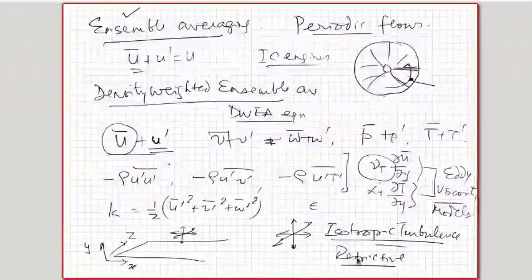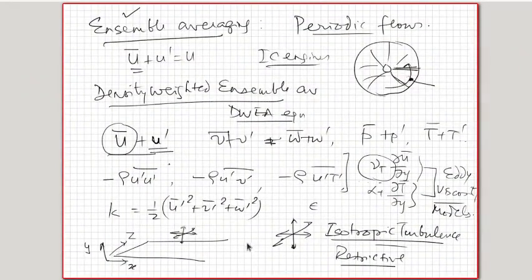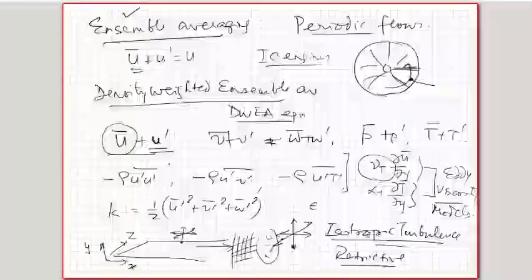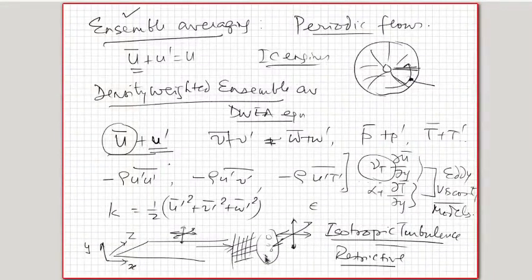Okay, what causes an isotropic turbulence is probably a grid. Say for example, if I have a wire mesh through which a turbulent flow leaves, and there are eddies which are of very similar size to the size of the mesh that are formed here. In this region, the flow will be isotropic, the turbulence will be isotropic. But other than the grid turbulence of this kind, everywhere else the turbulence is going to be non-isotropic. So the criticism of Eddy viscosity models is that they are not supposed to be working well for non-isotropic turbulence, but they should be good only for isotropic turbulence.